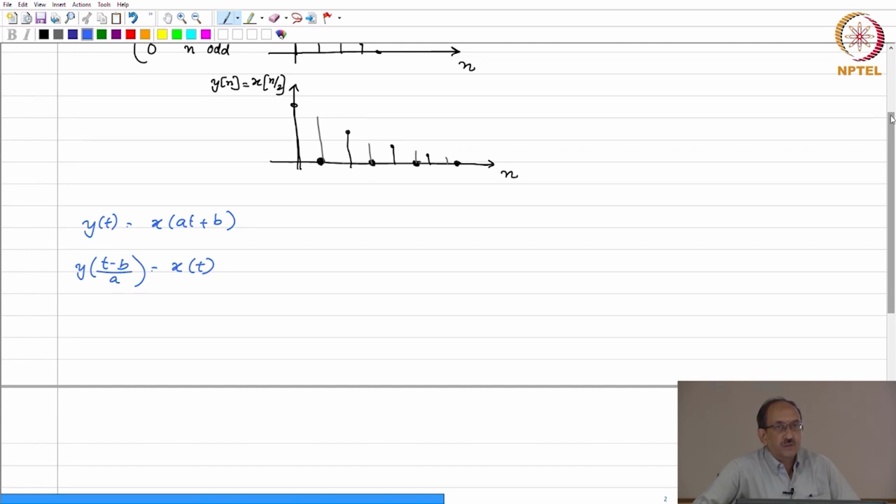So, if you oversample the signal, say by a factor of 2, then it stands to reason that you can downsample by a factor of 2 and yet not lose any information. So, it is not that downsampling always leads to loss of information. Under certain conditions, it is possible to recover the original sequence, but in general this is not possible.